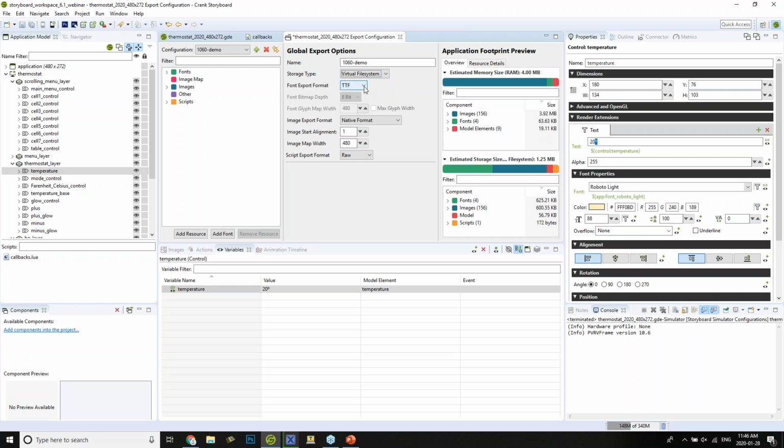And the other thing is you can choose if you want to have bitmap or TTF font rendering. The light projects that you saw in the SDK were using bitmap font rendering, again, reducing RAM usage. In our case, since we're configuring this for the real-time executive system, we're going to use the FreeType font engine that can support TTFs. And this is really good for building up rich internationalized products with different character and font sets.